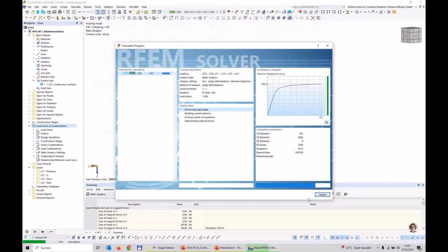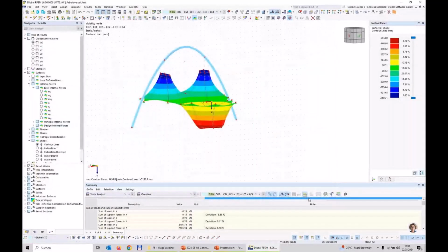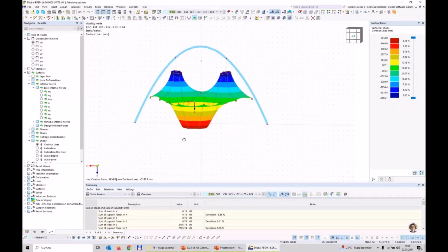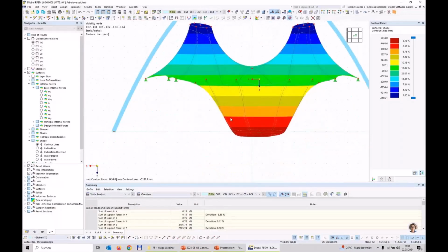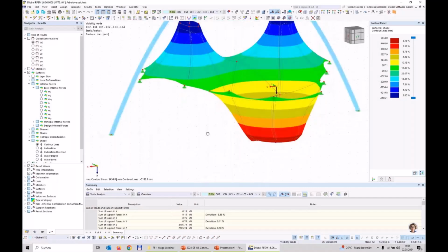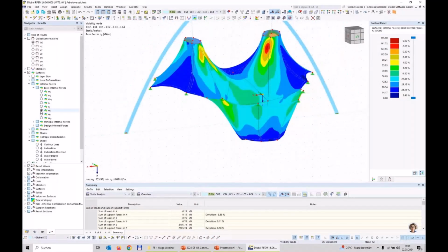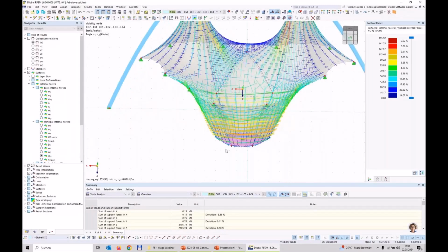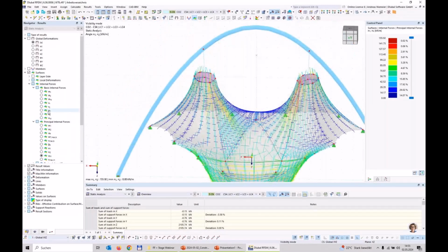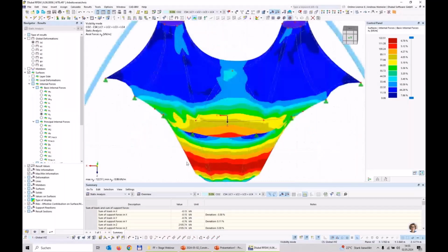It converged and it looks a little bit bulbous. If you take a look, these cones are sloped. This funnel is a little bit bulbous. And if you watch the forces, you see this band direction has really high tension. So if you simulate it here, you see our stress layout has some peaks. The tangential force is really high in the funnel.